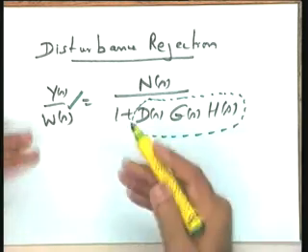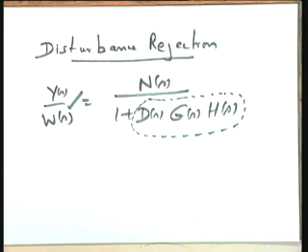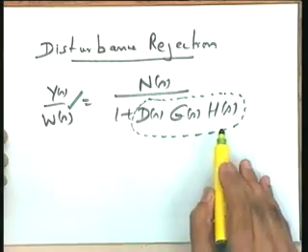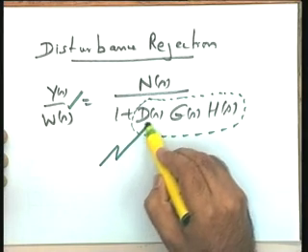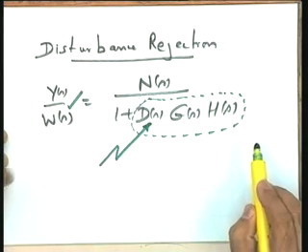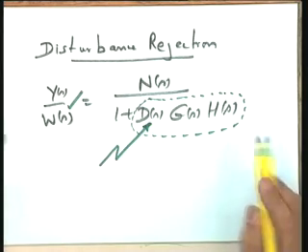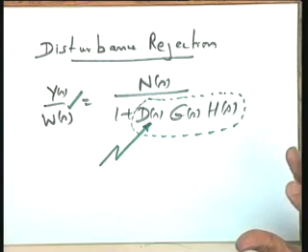If you make H equal to 0, the disturbance rejection is not possible. All the disturbances which enter the plant will definitely show up their effect in the output, because in the process of feedback your controller becomes intelligent because it has the information. You see that qualitative aspect of control action.